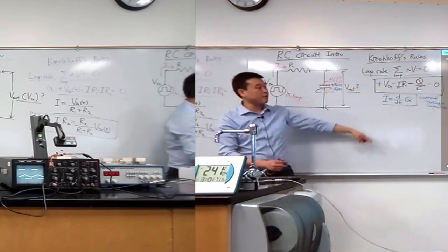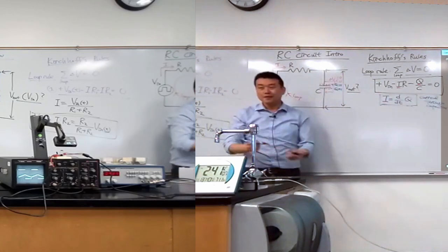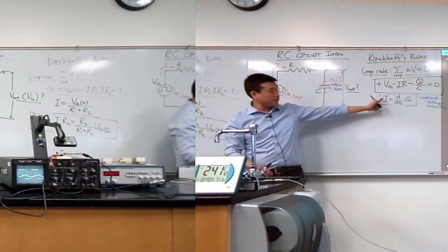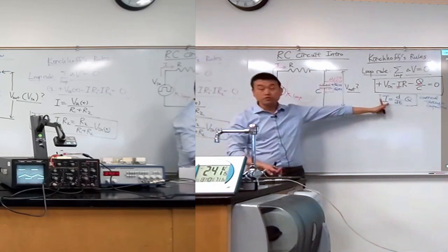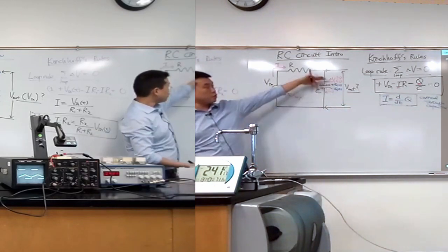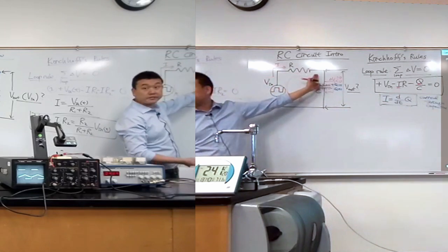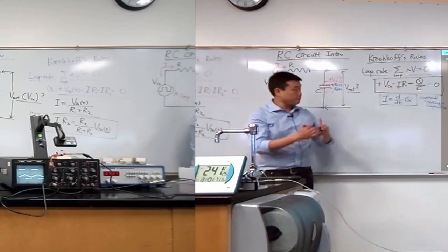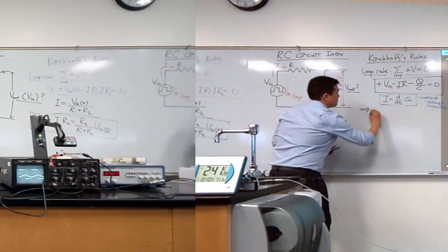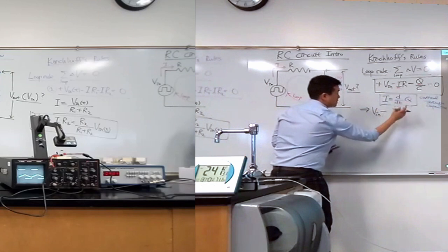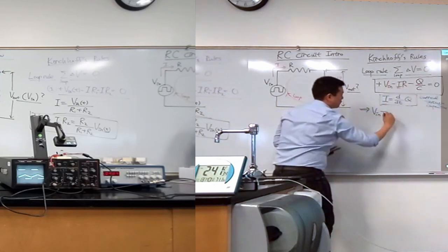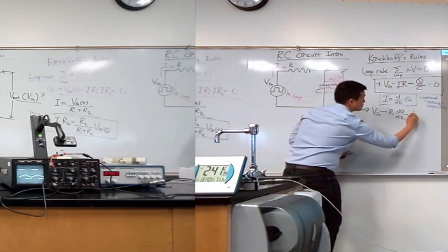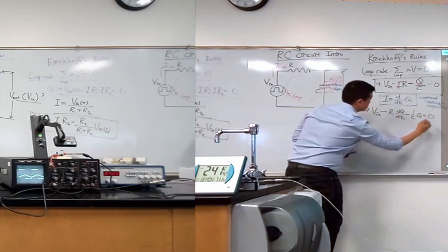So once all this is in a circuit, then I can write down this relationship that some of you are wanting to write down that I wasn't writing down until now. So this is the thing that relates, and even though this is the current through the capacitor, because this is one loop, current through the capacitor is the current through the resistor. So I can use this even for this I here. So plugging that in, this is what I end up with: V in minus this, or let me pull out R to the front, R times dQ/dt minus 1 over C, Q is equal to 0.